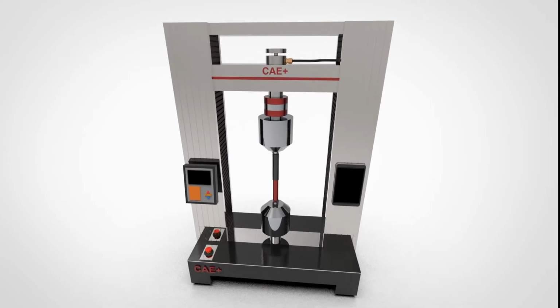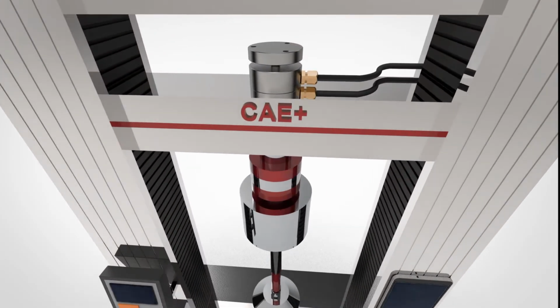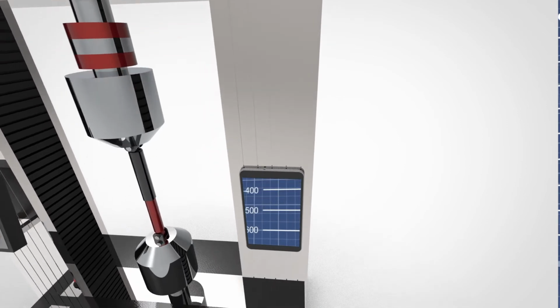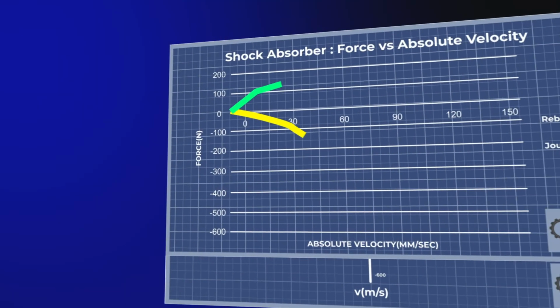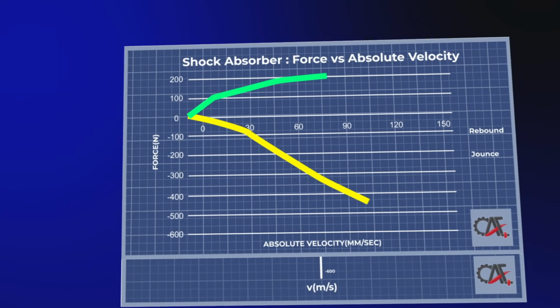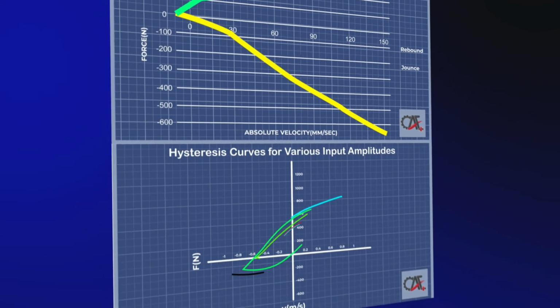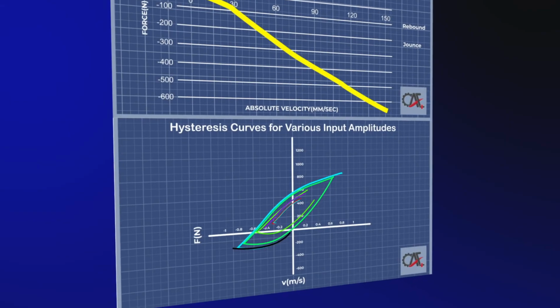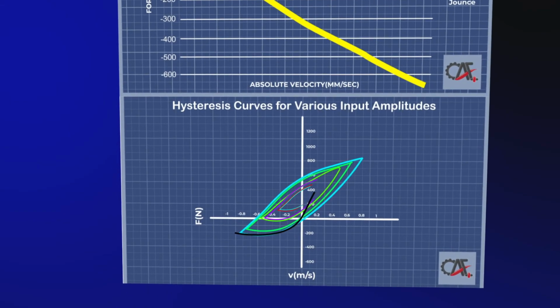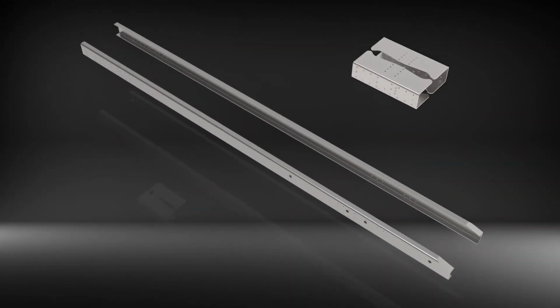For our example, the shock absorber must undergo an accelerated life testing or fatigue test to ensure its durability throughout the intended lifespan of the product. Meanwhile, special tests can be performed to ensure the dampening characteristics of the shock absorbers are up to par with the OEM and engineering standards. Once the required approvals are obtained from the design verification and validation steps, the product is ready for production.